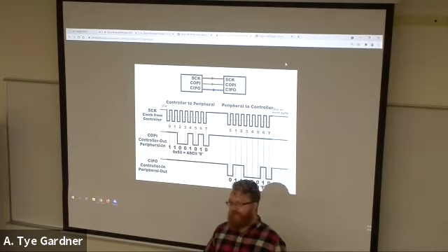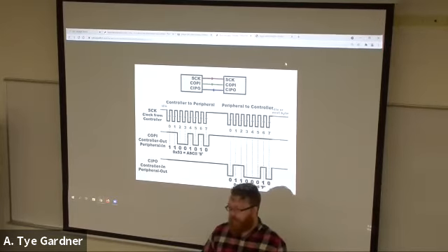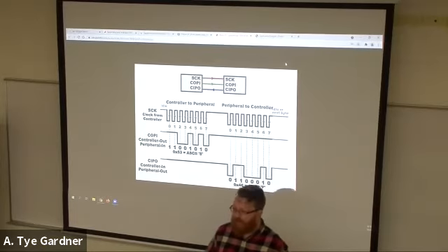Theoretically, you can get UART up to like 4 megabaud roughly if you're really careful. I've never pushed it past about 1.2. Well, just 10 times what we're at right now, actually. And even that, you start getting errors. And so then you'd introduce parity in error checking, right, and resend packets. It has problems. It is actually very difficult to get UART to go quickly.